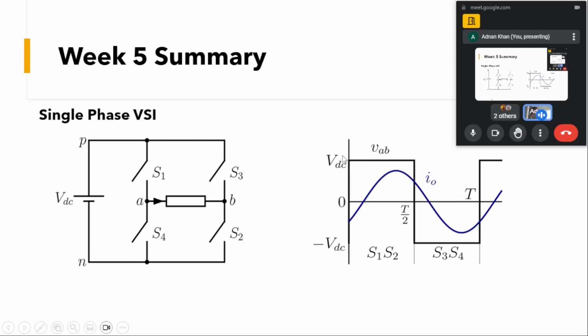And similarly, now this we were able to get due to this one leg, but now we wanted to have this negative voltage, so we can have an AC kind of a waveform which has positive as well as negative values, and here it is a kind of a square wave. So by switching on S1 and S2, we were able to have plus VDC voltage.